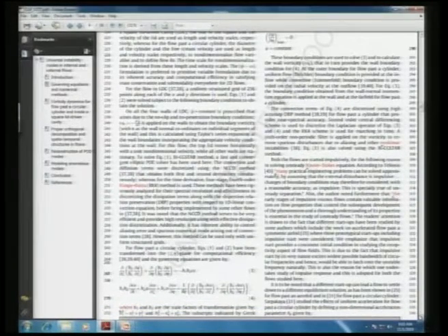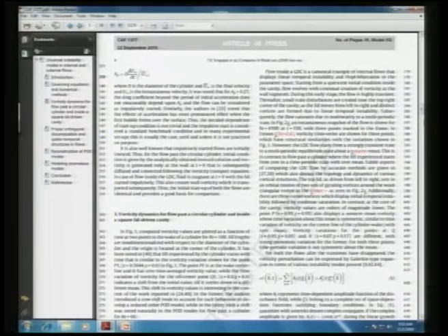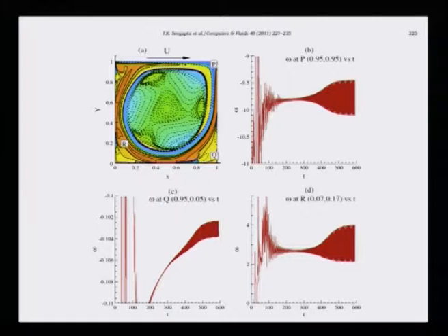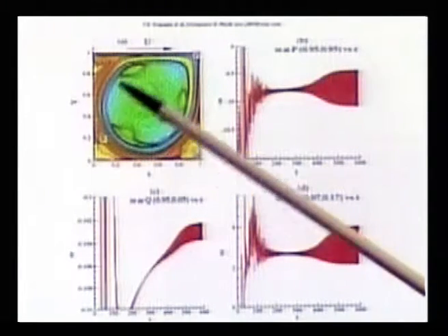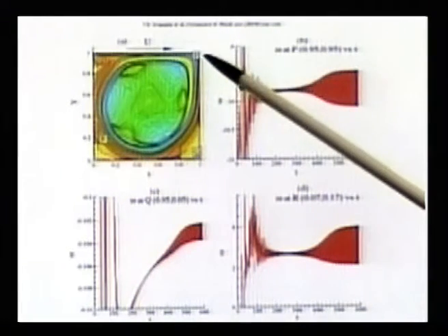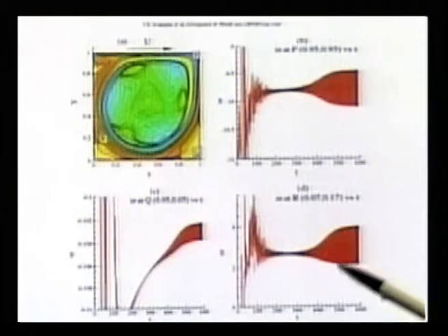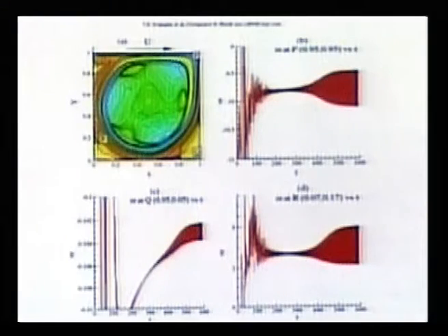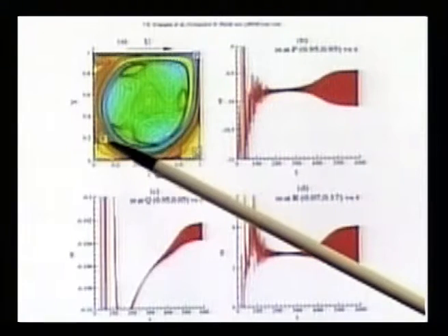We go through the same process of solving the Navier-Stokes equation and getting those solutions, then obtain the instantaneous flow, then obtain the mean flow, and then calculate the disturbance flow. Once you have the disturbance flow, you obtain those Galerkin projections that we are seeing, and this is what your driven cavity program is. What you have here is basically a square cavity. The flow is set up by moving the top lid from left to right at a constant speed u, and then we focus our attention on 3 representative points marked here. P is the topmost right corner point, Q is this bottommost right point, and R is over here.